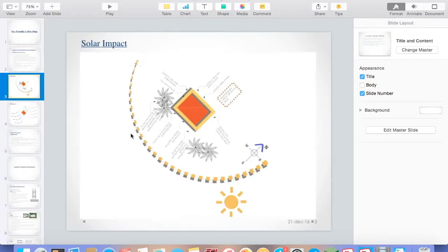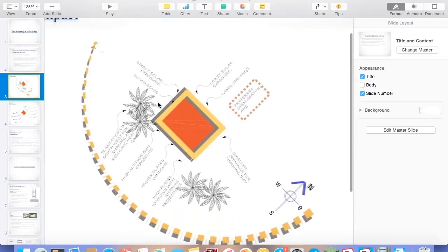See, this is the sun path. Now we can understand clearly that it is moving from east going to the west and through south. So this is the area which mostly needs to be protected. So we should try to have more plantations in this particular corner and more openness on this side. Let's zoom out a bit and we'll be able to have a better picture of it.